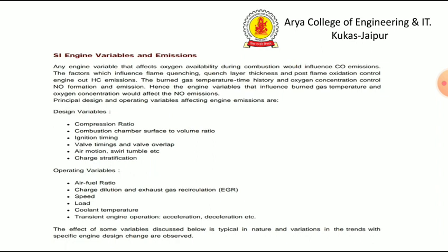The burned gas temperature, time history, and oxygen concentration control NO formation and emissions. Hence, the engine variables that influence burn gas temperature and oxygen concentration would affect the NO emissions.